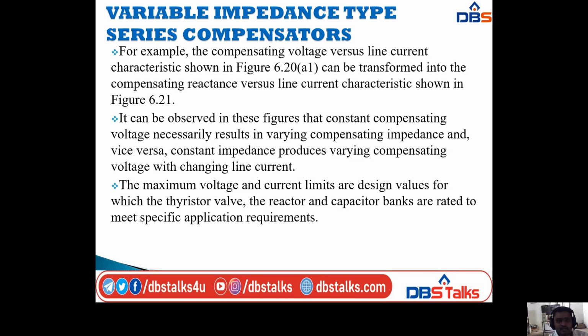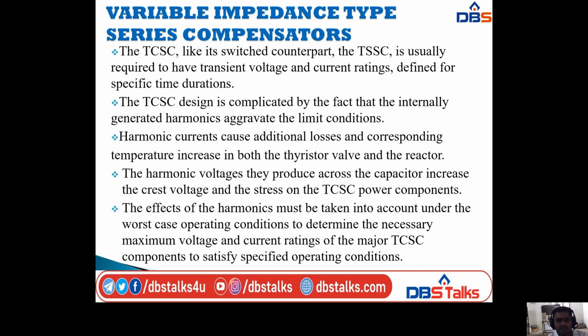Next, the TCSC, like its counterpart the TSSC, is usually required to have transient voltage and current ratings defined for specific time durations. The TCSC design is complicated by the fact that the internally generated harmonics aggravate the limit conditions.